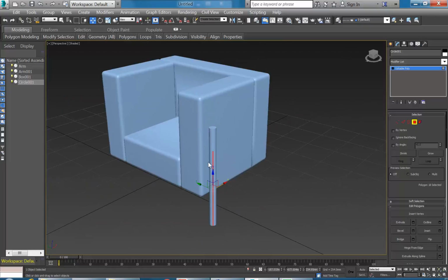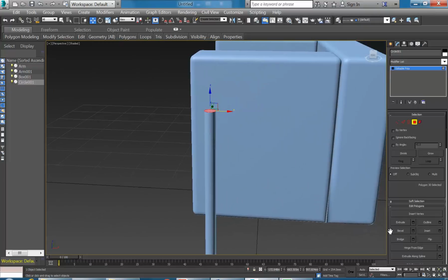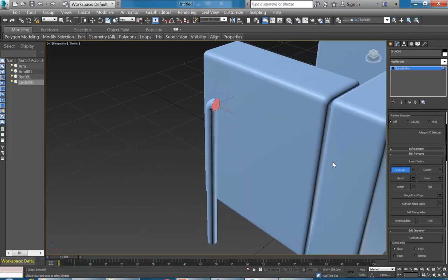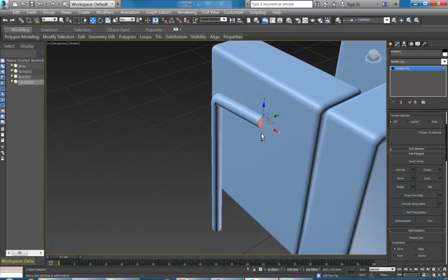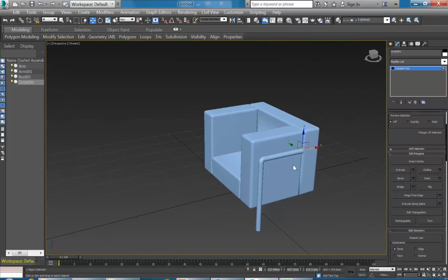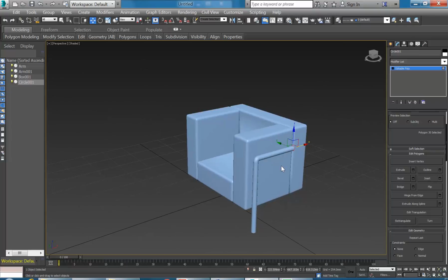And I can, again, maybe just do something simple like hinge to bring it around. Or, again, have a look at the settings and put in more segments as I do that, and then just continue extruding and using those other tools to build up. So you can model in a fairly free-form way, just using polygons, just thinking about the surfaces that you need to create.